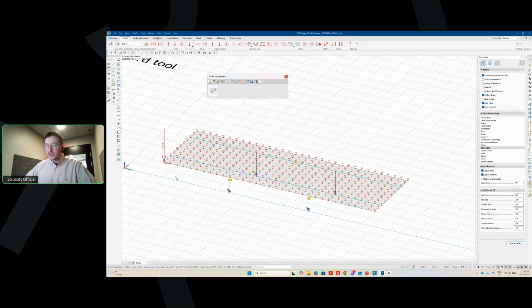And then in the end, it will solve the optimization problem to find the critical load position out of all of the available options. There are millions, of course, especially when we have these parametric vehicles with non-set distances. So it will look for the worst position, and then it will place the results based on the influence graphs. And then it will simply scale up the results that was calculated from this 1 kilonewton load.